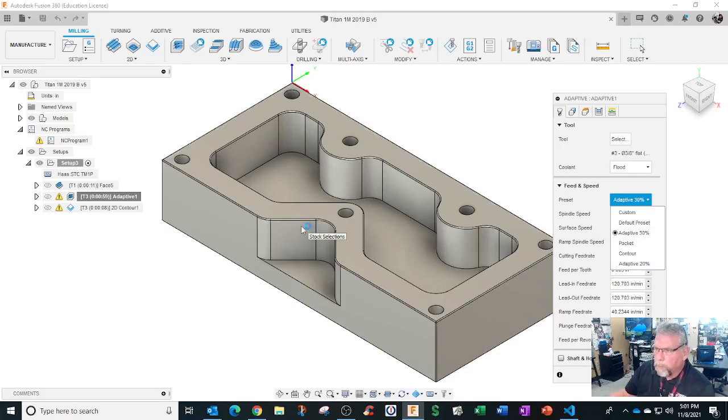Or face mill where they forget to do multiple steps. I actually have the machine set up to stop feeding when it gets 101% on the feed rate, so that the machine stops and just sits there spinning. They keep on hitting cycle start and it goes creeping along, and it just keeps on hitting 100%. But maybe like a poor man's way of crash prevention.